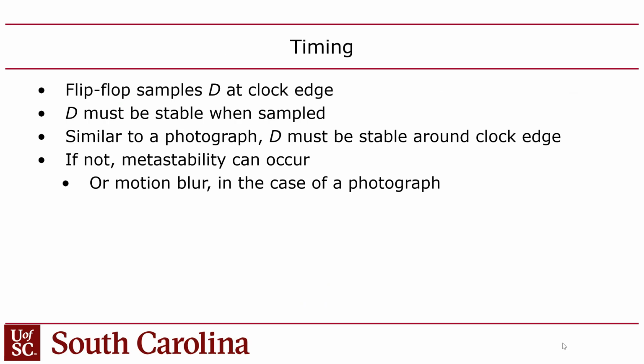I'm going to move on to another slight topic change here. We talked about flip-flops and how edge-triggered flip-flops, in theory, sample their input D on the rising edge, say, or on the falling edge. Usually, in this class, we just use the rising edge. And when you do your behavioral design in Verilog, you just assume that the flip-flop takes a snapshot of its input on the edge, and that snapshot is an infinitely small amount of time, so it instantly samples the input, right?